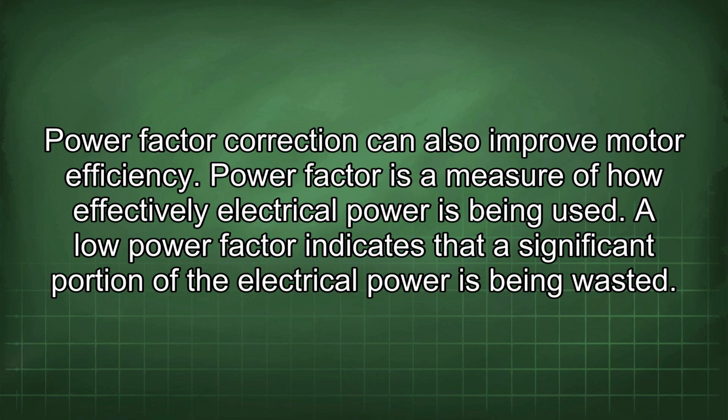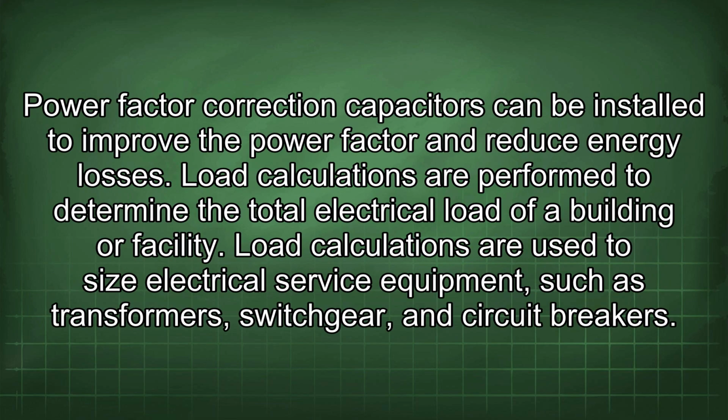Power factor is a measure of how effectively electrical power is being used. A low power factor indicates that a significant portion of the electrical power is being wasted. Power factor correction capacitors can be installed to improve the power factor and reduce energy losses.